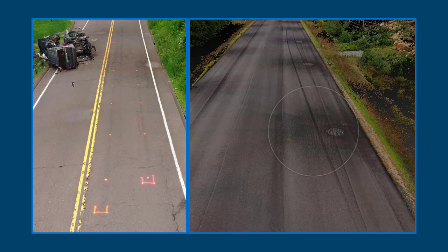And along the same line, Keith also says, most scans that I get do not show the skid marks very well compared to the photo of the skid mark derived from the scanner or other sources. Keith wants to know, is there a scanner setting that's causing that? It can be a scanner setting, but I think probably what's going on is that the scans are being taken in color, and typically it's in a situation where there's not enough light or there's too much light, and the skid mark is not visible because of the reflection or the bright light from the sun on the roadway. The best thing to do in that case is to turn off the color, look at that scan in grayscale, and then mark the locations of the skid in grayscale, and you can see them well there. There you go, Keith.